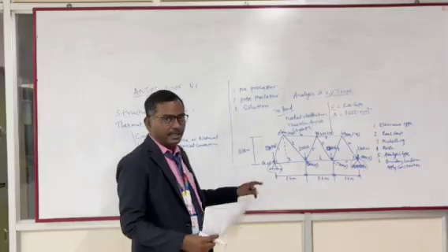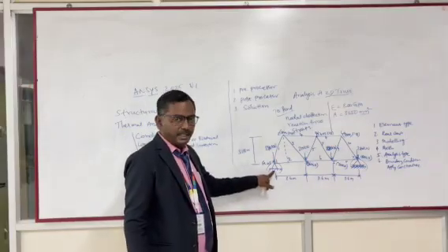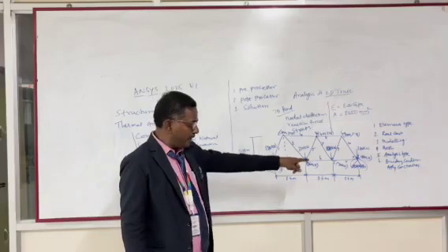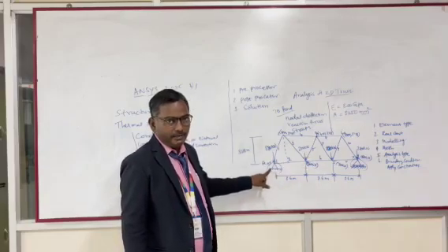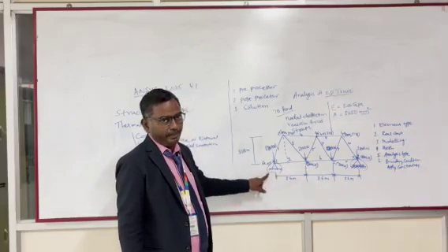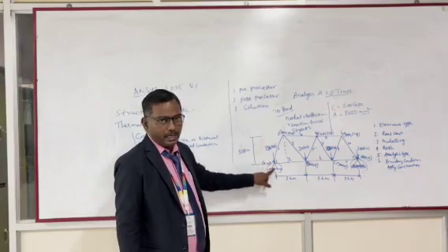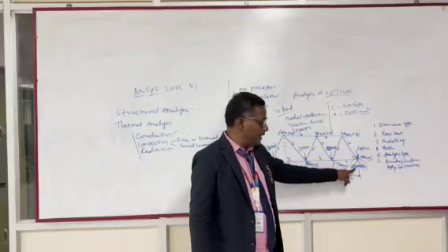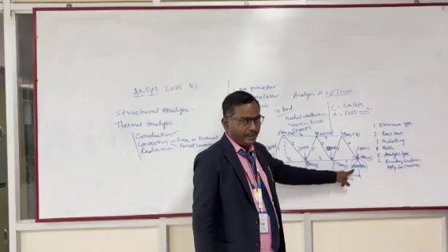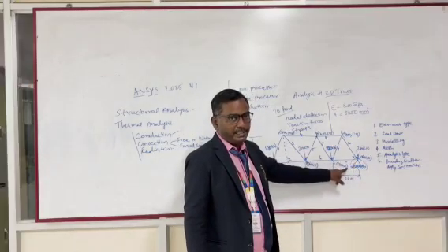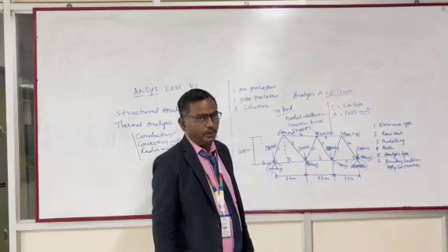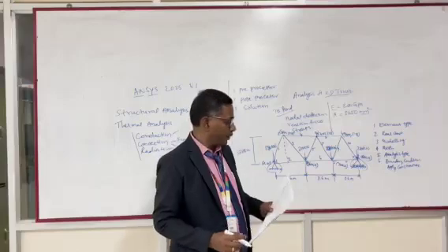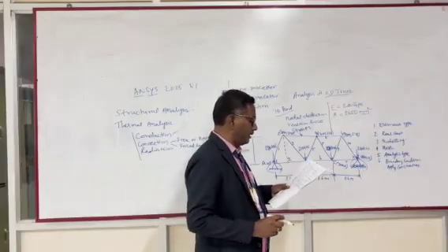So this is called as a constraint. This constraint you can give as, so this is a fixed support. So we are going to arrest, applying constraint, selecting apply constraint, we are arresting all degrees of freedom. In the fixed support, we are going to select all degrees of freedom as arrested. Okay. So here it is a roller support. So the x-axis moving. So y-axis alone, we are going to select the constraint. Okay. So it is a fixed y-axis. We are going to fix the roller support. So this is the another point.